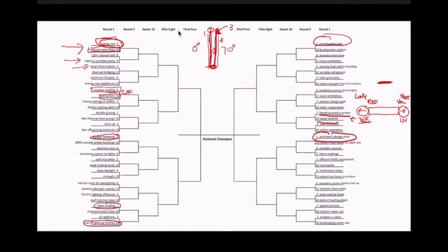So what a low E film does, and this is kind of a crazy concept, is that in the infrared spectrum it acts as a mirror. To the heat, it looks like a mirror and it bounces off. So if it was 100 degrees outside and sunny, the heat would hit that mirror and a lot of it would bounce off. But most of the light, most of these frequencies between red and violet, but not all of it, will pass through. So low E coating allows the light to pass through, but looks like a mirror to the radiant heat that comes through from the sun.